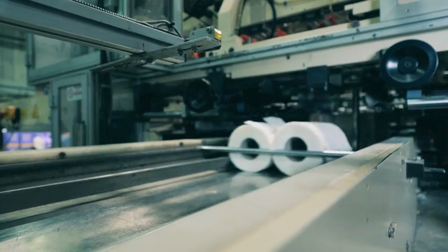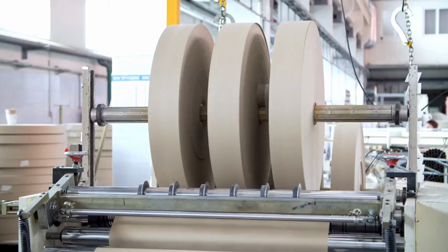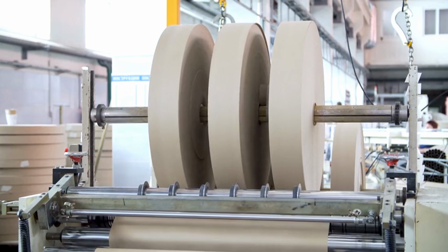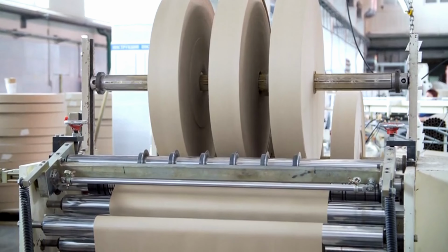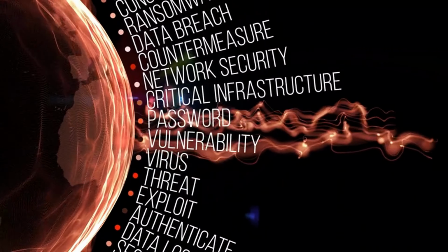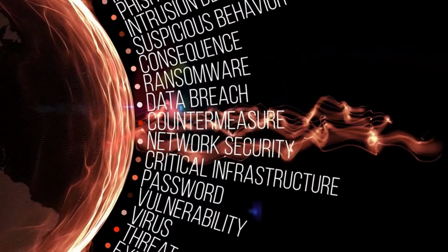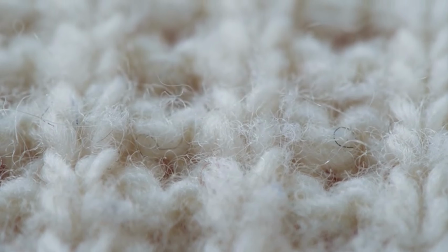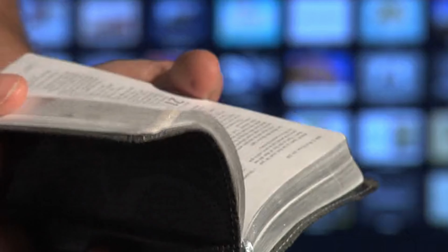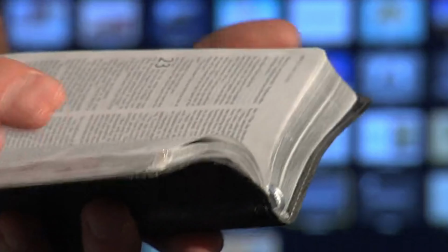6. Specialized paper manufacturing. Mills produce custom paper products using advanced techniques. A. Security paper, such as banknotes and certificates, uses watermarks, security threads, and embedded holograms. Fibers include cotton and polymer blends for durability. B. Ultra-lightweight papers, used in Bible printing and airline manuals, require precise fiber blending and ultra-thin coatings.